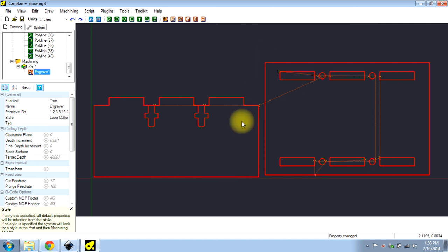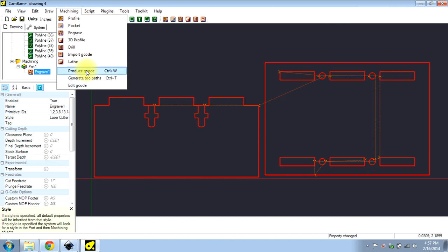If this were a CNC, I could hit Alt and grab the drawing, and I can flip it around, and I can actually see the cut lines going down in succession. I can see everywhere it's going to be, and I can get a really good idea if, for instance, there's a cut line 5 inches down, you realize that you typed in 5, not 0.5, and your machine is going to cut all the way through its table trying to go 5 inches deep. You can see it all right here and fix it quickly.